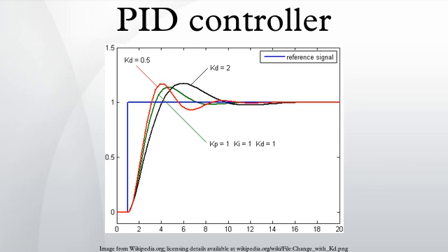Reciprocal gain. In many cases, the manipulated variable output by the PID controller is a dimensionless fraction between 0 and 100% of some maximum possible value, and the translation into real units is outside the PID controller. The process variable, however, is in dimensioned units such as temperature. It is common in this case to express the gain not as output per degree, but rather in the form of a temperature which is degrees per full output. This is the range over which the output changes from 0 to 1.